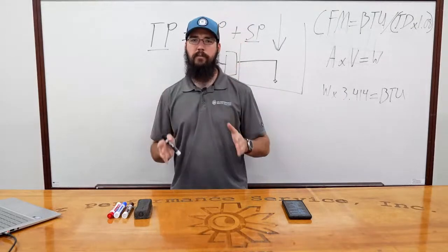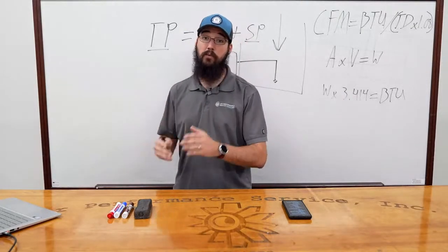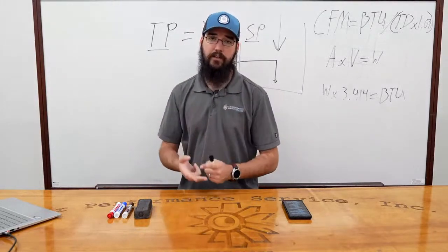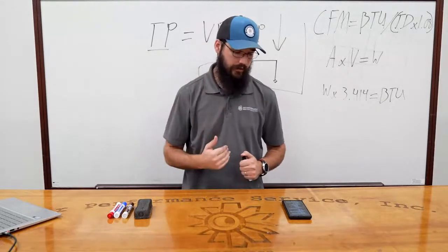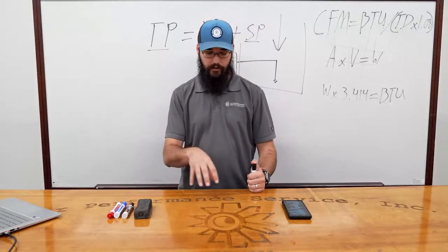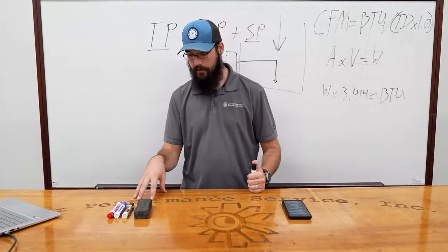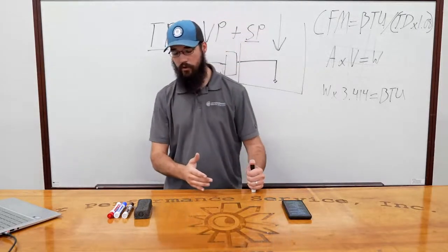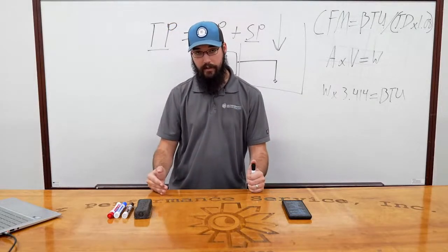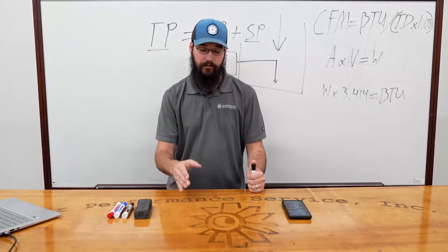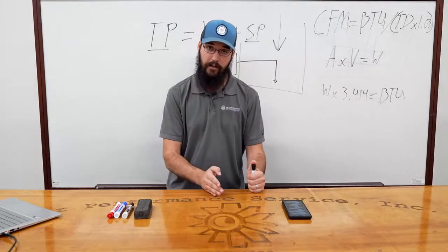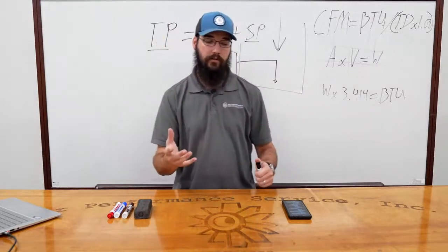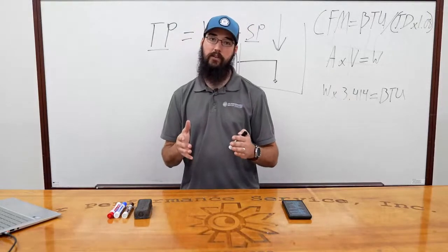But on a fundamental level, let's say those things were not problems, or you got to the site and you confirmed the fan's working great and the coil's perfectly clean. So that's not part of your problem, right? In that situation, if you've got low airflow, that's the same thing as low load, because it's the amount of heat we're giving to the evaporator. Because we're giving the evaporator less heat, we're going to see lower readings in the evaporator. So your saturation and superheat will both be low, or technically could be normal. It's not uncommon that the TXV has the ability to catch that.